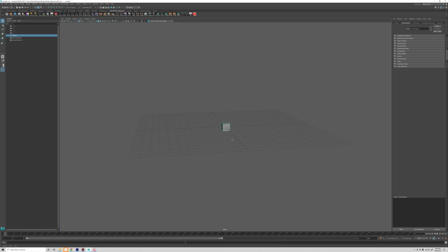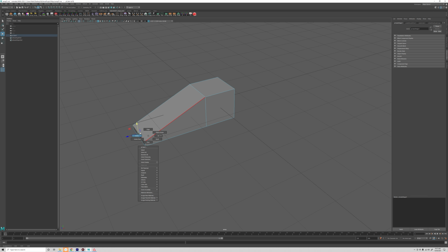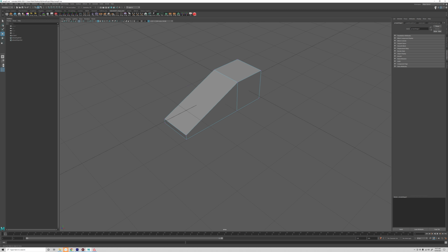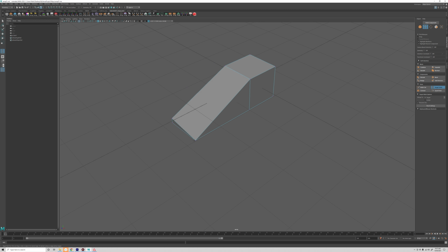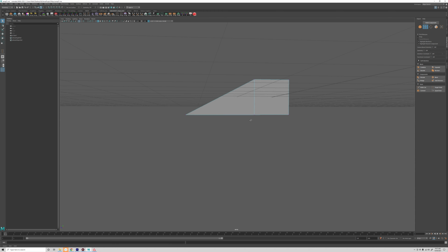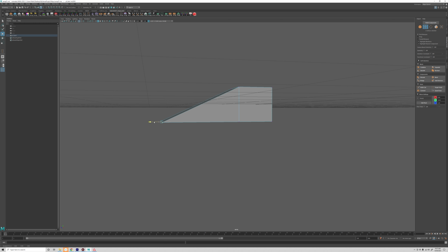I'm going to make a very simple object. Now in Maya, the grid is set to single unit is a centimeter, so this is a 1 by 1 centimeter unit, and all I'm going to do is a very, very simple model of just make it a basic ramp. I just want a little bit of an extended piece, grabbing this edge, dragging it down, and what I might actually do is just merge these verts. So I'll go into vertex mode, just jump over to my modeling toolkit and select target weld, and I'm just going to grab these verts and drag them down. Hit Q to get out of that target weld tool, and that's about all I want. Pretty simple, but that gives us a platform for the character to run up. I might just make it a slightly less steep angle just to be safe and keep it simple.